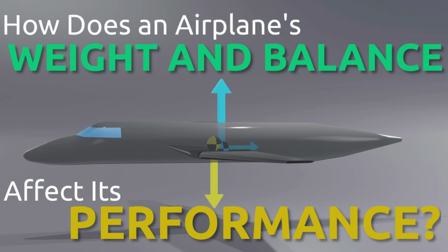Most modern aircraft are so designed that, when all seats are occupied, the baggage compartment is full, and all fuel tanks are full, the aircraft is grossly overloaded. This type of design requires the pilot to give great consideration to the requirements of each specific flight. If maximum range is required, occupants or baggage must be left behind, or if the maximum load must be carried, the range, dictated by the amount of fuel on board, must be reduced.